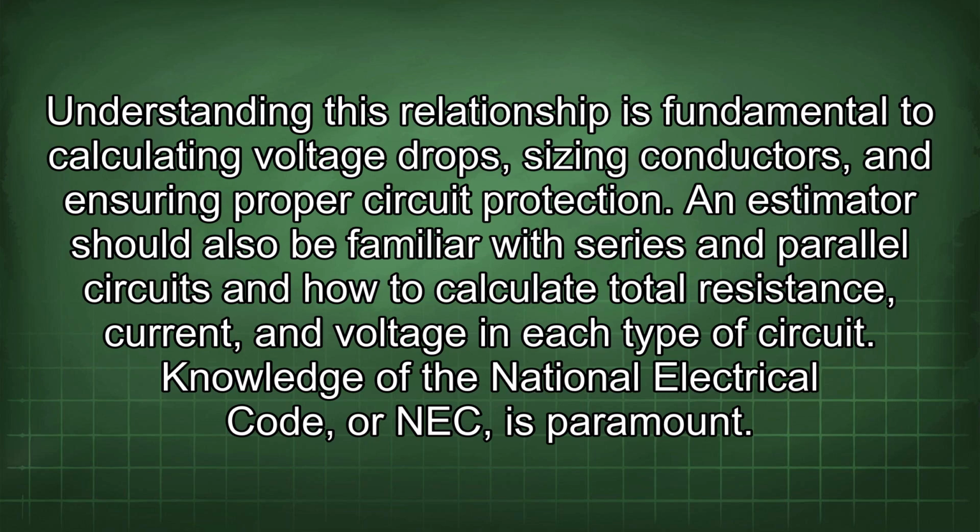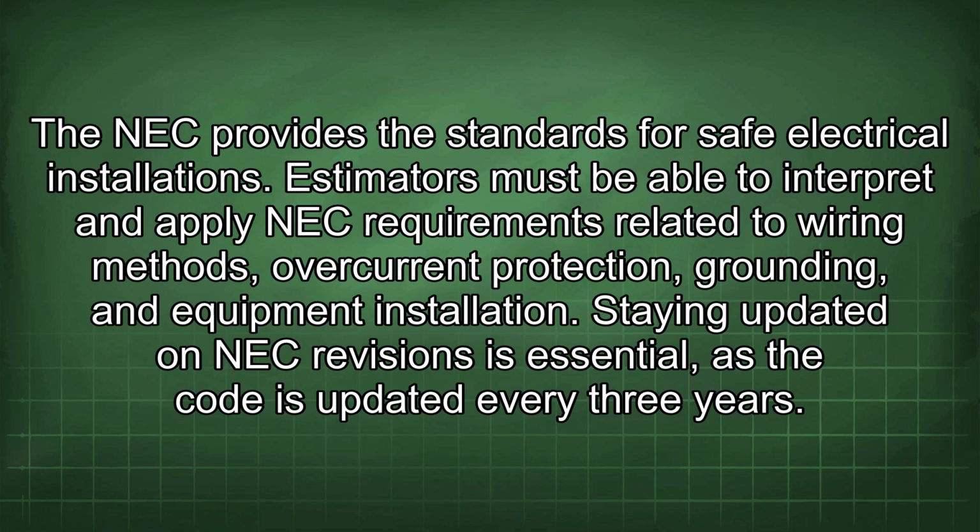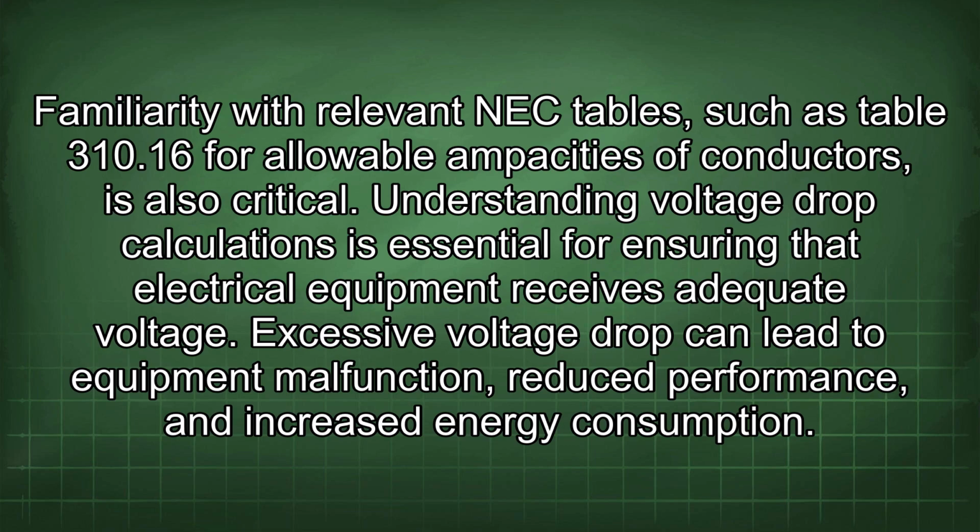Knowledge of the National Electrical Code, or NEC, is paramount. The NEC provides the standards for safe electrical installations. Estimators must be able to interpret and apply NEC requirements related to wiring methods, overcurrent protection, grounding, and equipment installation. Staying updated on NEC revisions is essential, as the code is updated every 3 years. Familiarity with relevant NEC tables, such as Table 310.16 for allowable ampacities of conductors, is also critical.